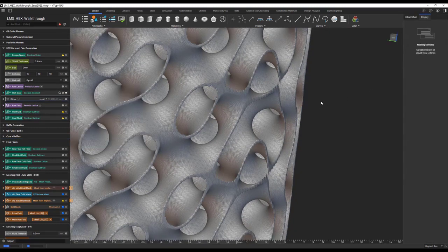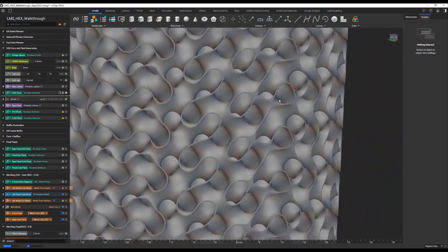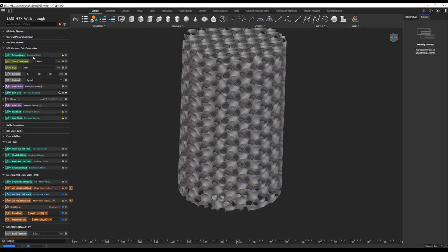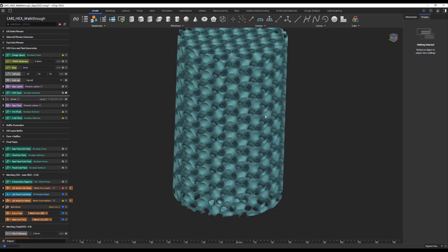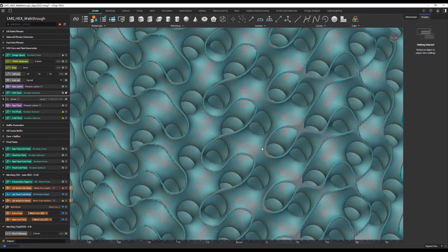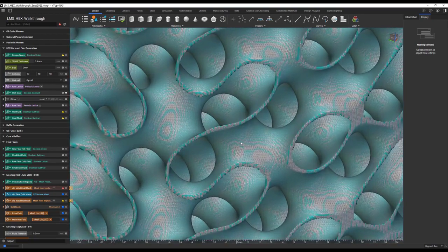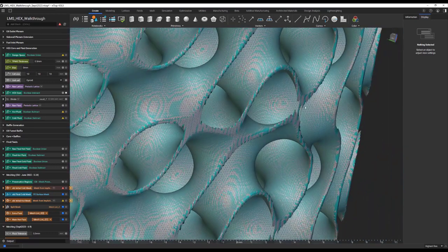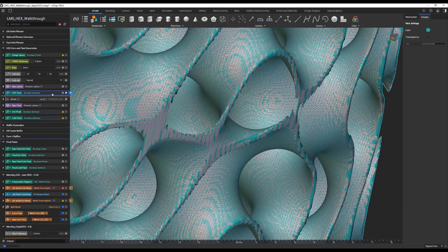And you'll also notice that I'm only meshing the hex core rather than the shell and everything associated with it. There's no real reason, at least in these initial stages, when we're going to do the conjugate heat transfer analysis, to mesh the entire solid domain. That's just wasted elements and wasted computation time, where we really just care about what's happening between the two fluid domains. There might be a few thin sections that we have to resolve in the mesh to help clean that up.